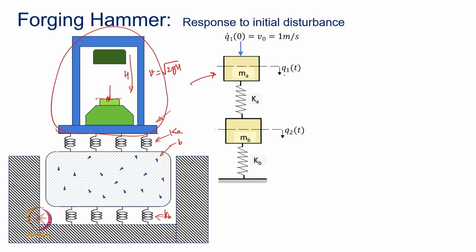The 2 degrees of freedom, right now we are constraining that it moves vertically up and down, that is it. Now, we are not considering other motions, just for the sake of simplifying the solution process. Makes sense also, if it is properly symmetrically located, any vertical excitation is largely going to generate a bounce motion.